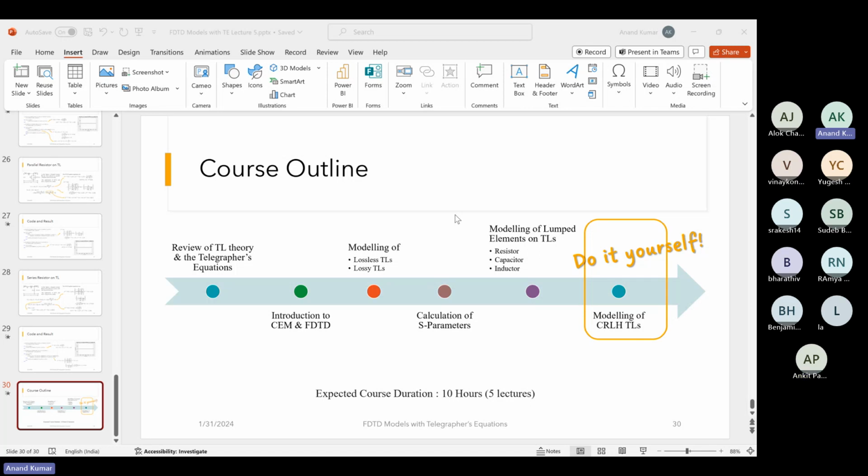it will be very computationally expensive if you write 3D codes to do that. I'll recommend resorting to existing solvers because they are more efficient. But using FDTD, you can definitely do it. There are some examples on the MathWorks website which you can directly download and run. There is an example for a filter, and there is an example for a patch antenna as well. It takes very long to simulate those things, but it is possible.